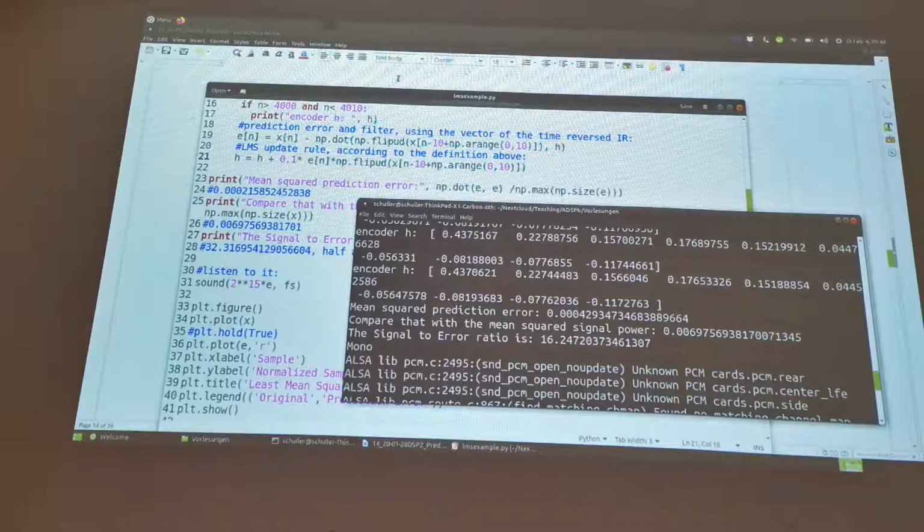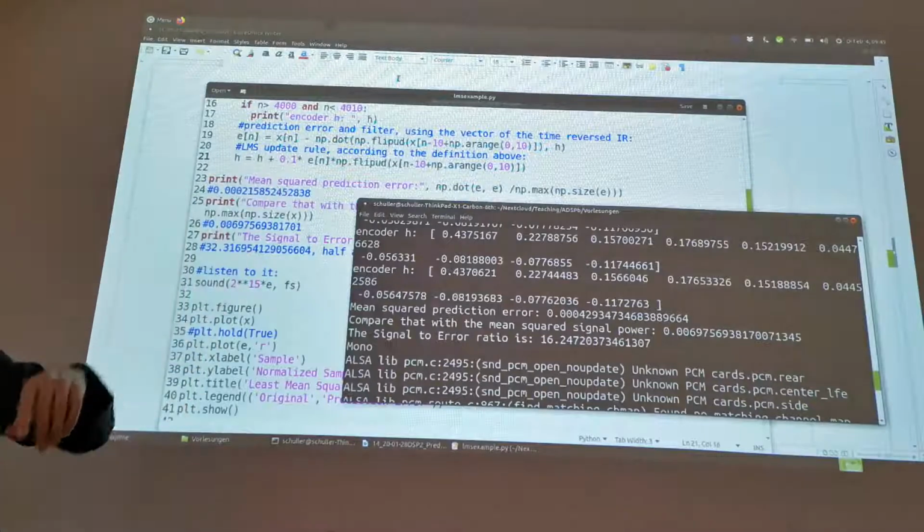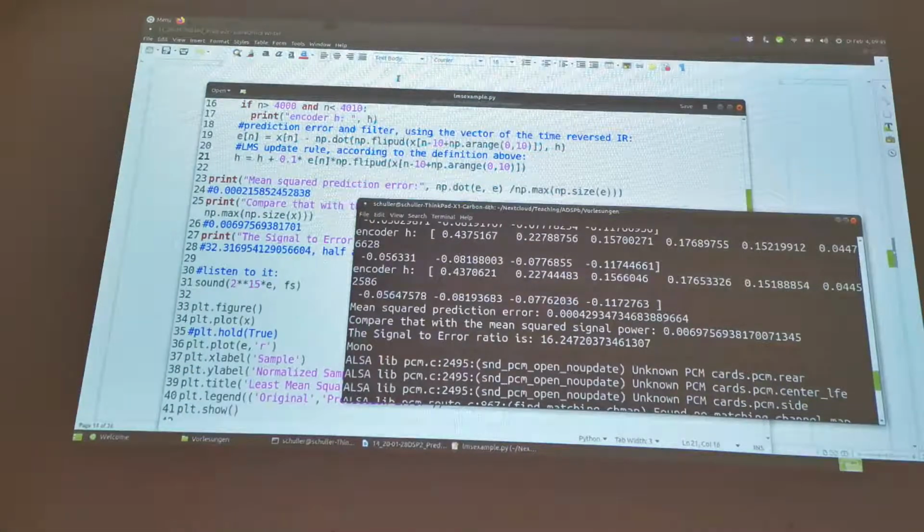Maybe if we found some adaptive way to change the alpha as the signal is being processed. Yeah, actually, in general, this is a good idea to adaptively change alpha. It's just a question how you would change alpha if you encounter instability. Because if you encounter instability, then it's usually too late because the encoder has a fixed alpha and the decoder cannot say to the encoder, now change it to some other value. Right? So in general, it's a good idea. It's just not clear how we would apply it here.